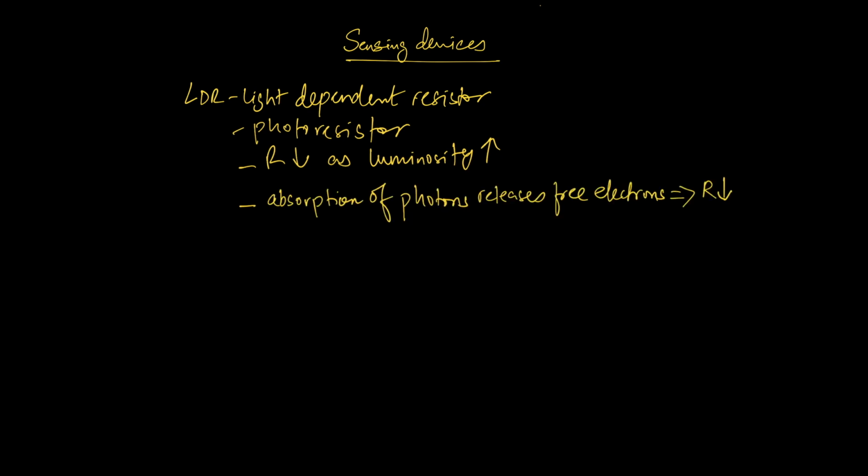When you have resulting free electrons, they conduct electricity, and that essentially then lowers the resistance. Another interesting thing about photoresistors is that they exhibit a little bit of lag, a little bit of latency between exposure to light and the resulting decrease in resistance, which can be on the order of a few milliseconds. The lag time when you're going from a lit environment to a dark environment is even greater. It can be as much as 1 second. And that property makes them unsuitable for sensing rapidly flashing lights.